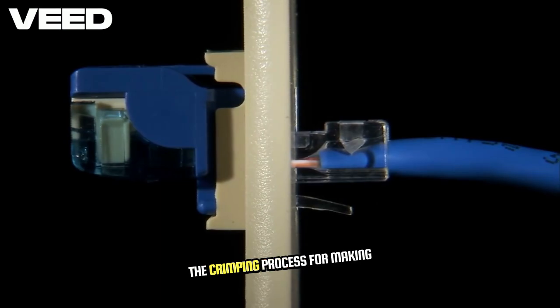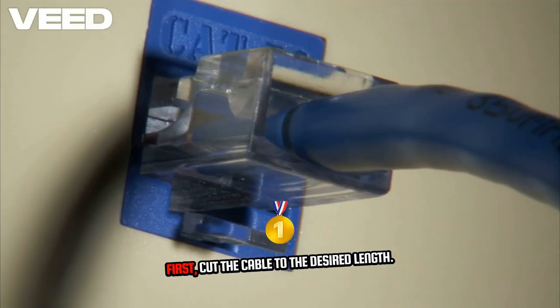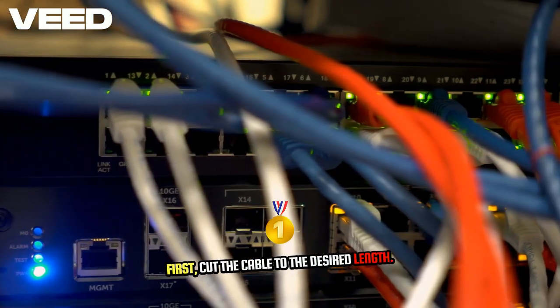The crimping process for making Ethernet cables involves several steps. First, cut the cable to the desired length.